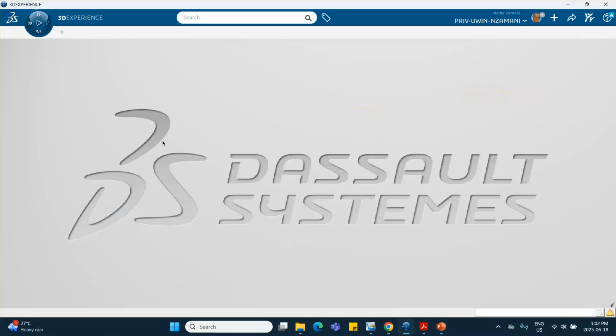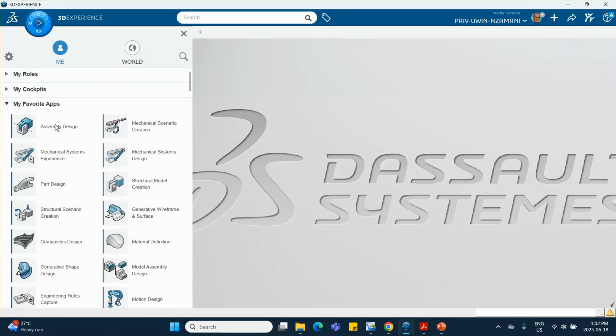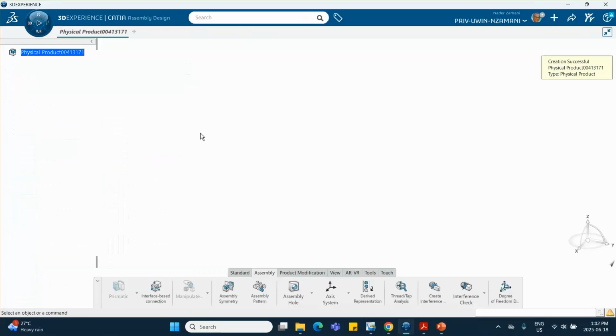All right, let's start with an assembly. Notice that for this problem, I can create a prismatic joint between the block and the wall, and that's exactly what I'm going to be doing, but it can also be done without a joint. Then, of course, you have to deactivate the gravity if it's in the wrong direction. But anyway, we're going to create a prismatic joint.